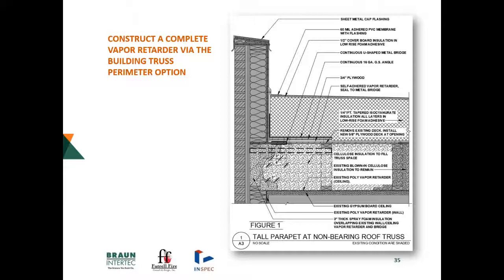And what we designed was a metal connecting bridge, a continuous metal connecting bridge to come up on the top side of the deck. Of course, once we cut the deck and bring a metal piece through the deck, we've kind of taken care of the structural integrity of the parapet, kind of cut the tendon, if you will, of the parapet. So our structural engineers had us go back and put some plywood on top of the vapor retarder system, and then some sheet metal angle work to reconstruct or resupport that parapet. So that's generally what had to happen all the way around the building.